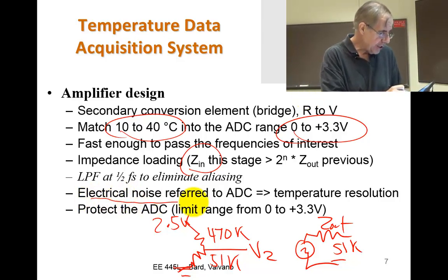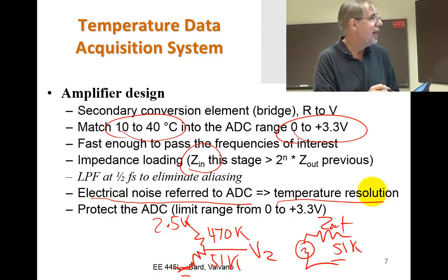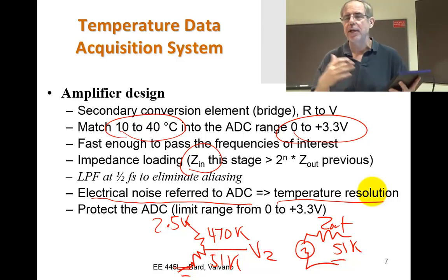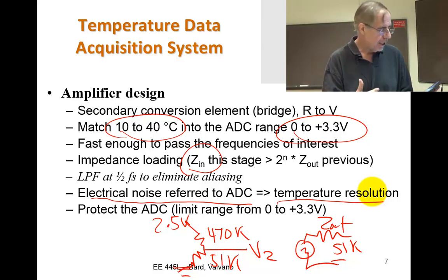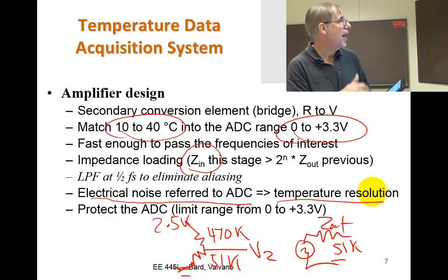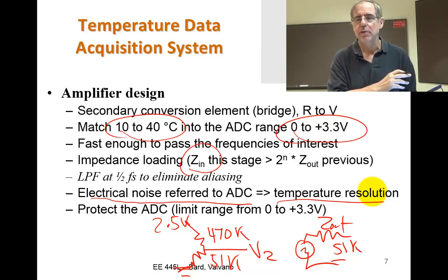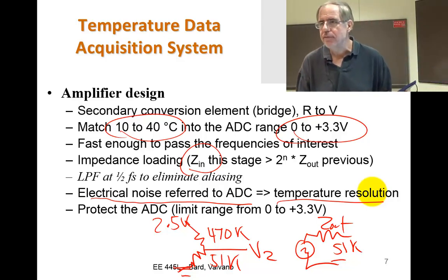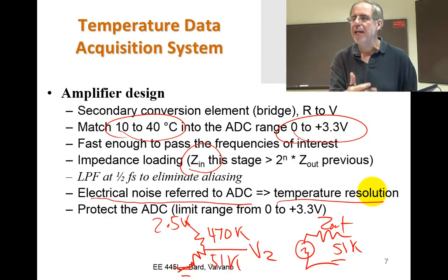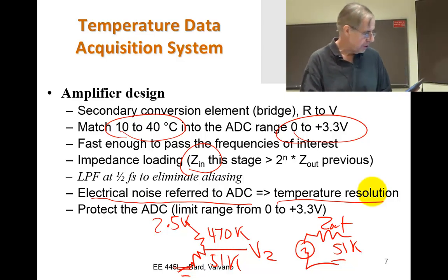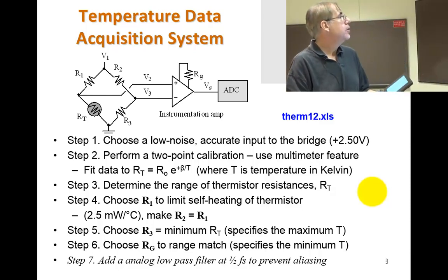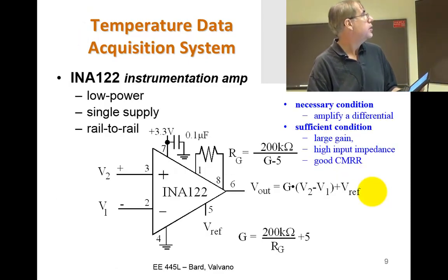And this is also important for life. If I look at resolution, which is the smallest change in my ability to detect temperature, it's going to be determined by the electrical noise, converted to the equivalent voltage or temperature or whatever. That electrical noise will determine the resolution of your system. All right, that's what I just did. So there are the rules, what I just did.